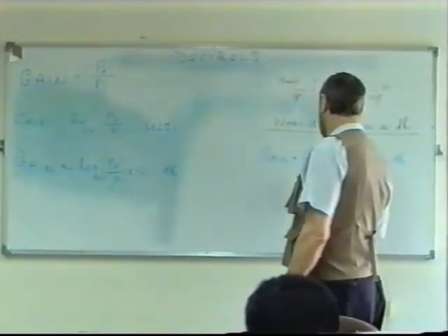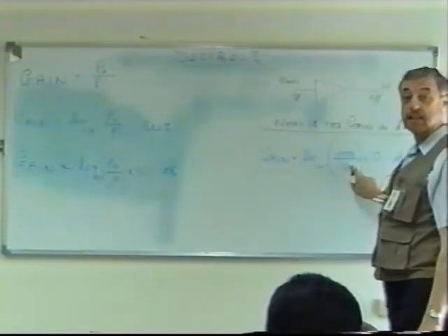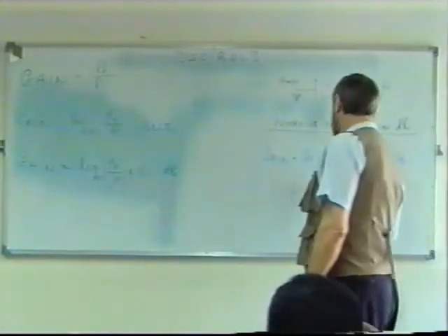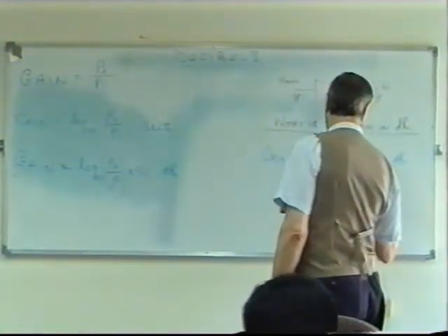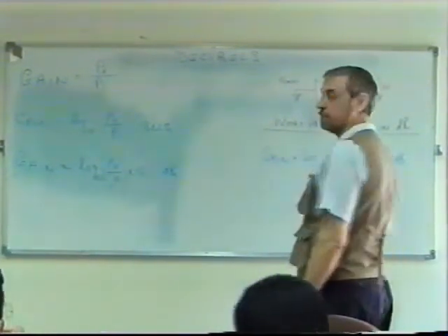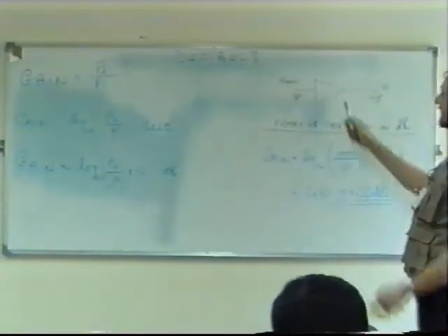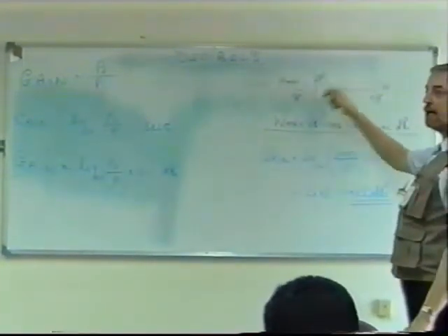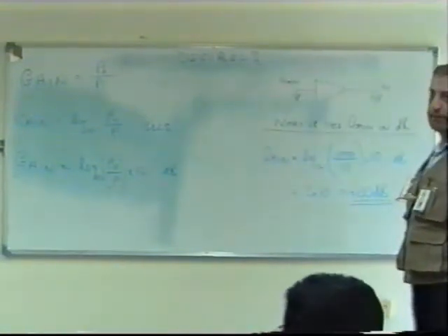So the logarithm of 1,000 over 10 is 100. Logarithm of 100 is 2. So it's 2 times 10. Right, equals 20 decibels. There's no negative number there, it's all plus. You can put the plus in front if you wish to make it clear that it is plus. It's a gain, a positive gain. We're adding power. We've got more power output than we have at the input.